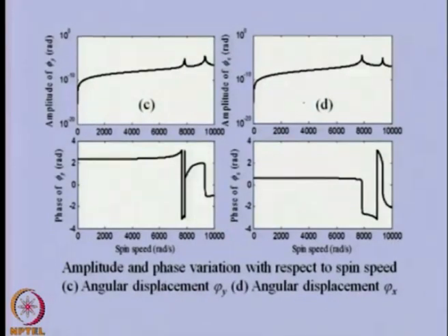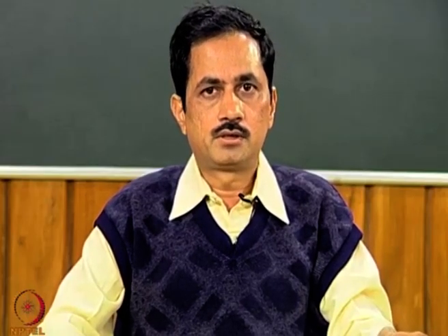In today's lecture, we have seen initially the basic concept of the hydrodynamic bearing, how the bearing fluid film forces impart stiffness and damping, and we have defined the stiffness and damping, both the direct stiffness and the cross-coupled terms, which couple the motion in 2 planes.